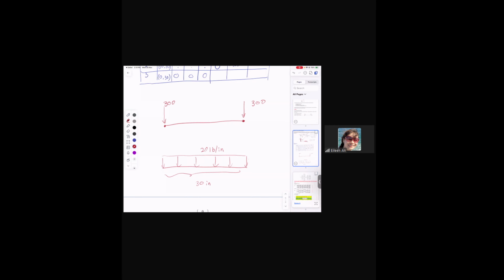We have to apply a moment, and those 2 moments will bend the beam, but won't generate any extra forces, right? Okay, so it is very important. When we convert this distributed load to its equivalent load, you cannot just look at the force. You have to have a look at the moments as well.